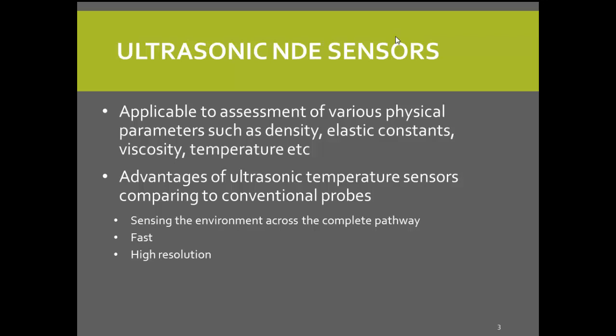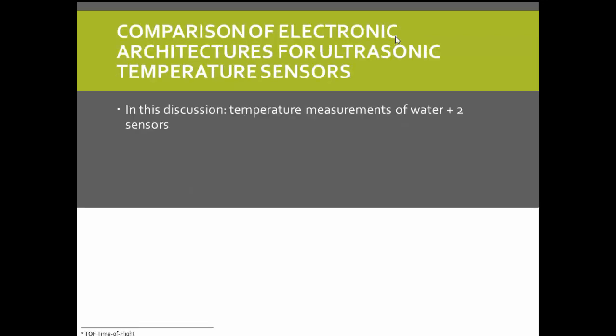they can potentially produce high resolution measurements. So in our application, we achieved a resolution of, worst case scenario, 100 ppm, and the sensitivity of temperature is about 1000 ppm per degree centigrade. So our resolution for this sensor is about 0.1 degrees Kelvin, which is much better than the available inexpensive conventional temperature sensors.